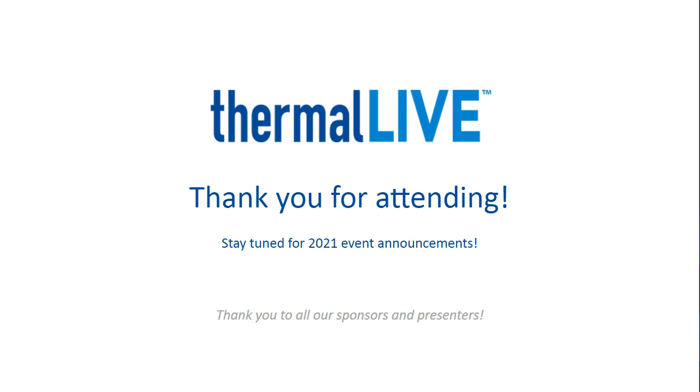Okay, well, moving on back to jet impingement, we have a question. How relevant is the liquid jet impingement for cooling electronics components? Yeah, similar to the previous question, liquid jet impingement is a way to cool localized high heat flux sources. You really need to have a high amount of energy that you're trying to remove in a very small amount of area to justify that exotic of a cooling solution, for most of the reasons I had mentioned previously.